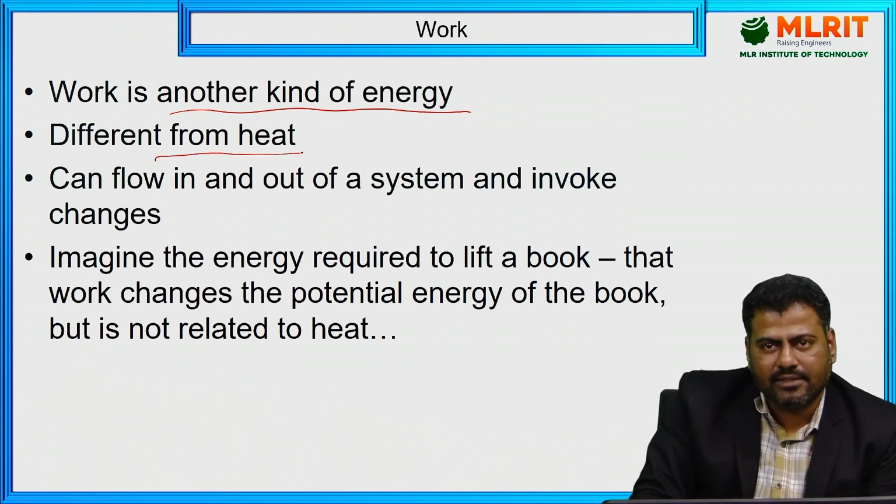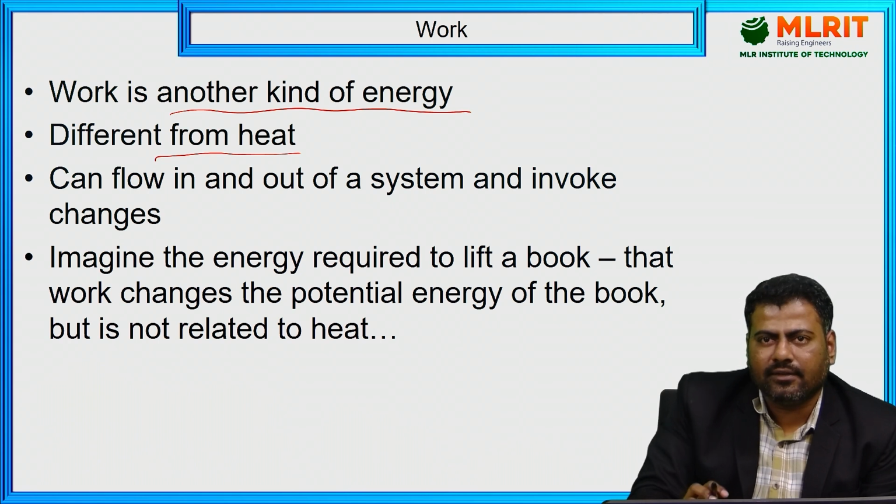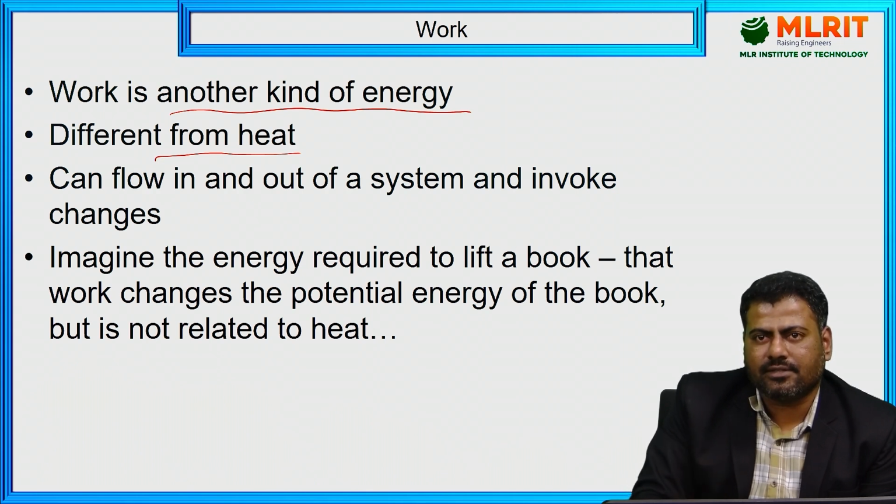So in order to sense the mechanical work done, we require movable boundaries, right? If I am considering a movable boundary, how much pressure is acting on it? The pressure can be obtained from the momentum of the working substance, and I can convert that pressure into a force parameter also. So this much load is acting on the movable boundary. Got it? And how much it gets displaced with respect to that, I can sense the energy. So this is what we call the mechanical work done.